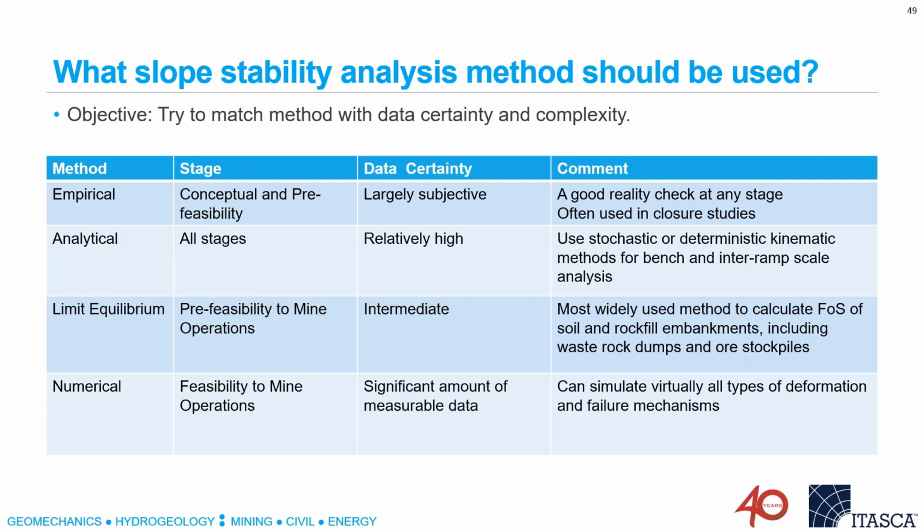Analytical methods, I think, are really good looking at bench and inter-ramp scale problems that are structurally controlled. And obviously bench designs are the most obvious, but some inter-ramp problems can be analyzed with analytical methods, and I think are very good for that.